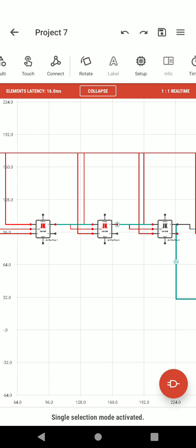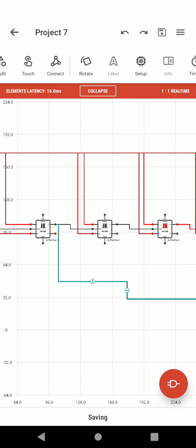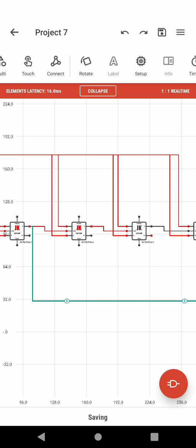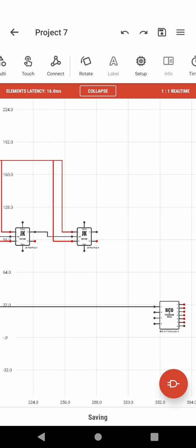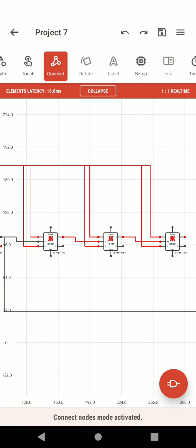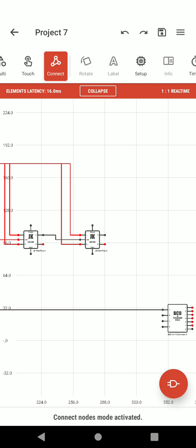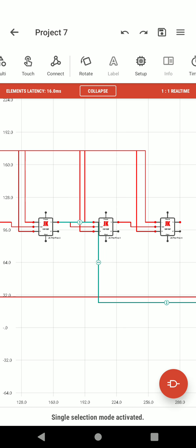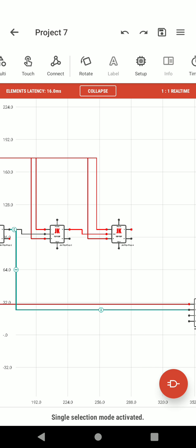Sliding is very important. Just slide it down. Just click at any point. So now again, Q of the second flip-flop to B. Connect Q of the second flip-flop. We have to press exactly at the dot. So just slide it. We have to see which connection is which.